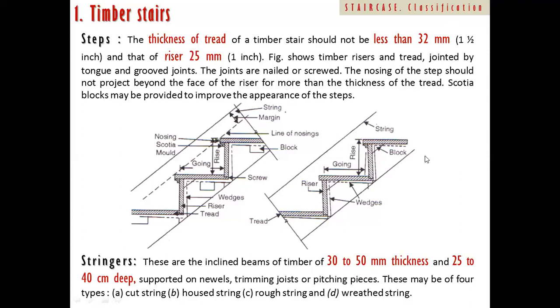So you can imagine the timber joist. A timber joist is nothing but like a beam, which in timber construction is called a joist. And then the other member here will be the newel. So the string is connected to the newel and to the timber joist, and within that it takes a fixed position. With the help of the stringer, one stringer is placed on both sides of the tread and riser, and later the tread and riser get housed in the stringer.